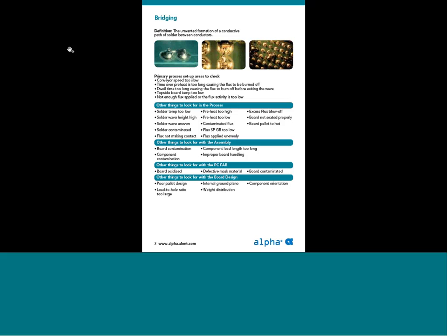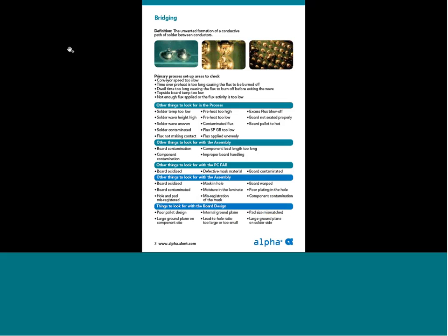Board design: internal ground plate, weight distribution, component orientation. Many times we can troubleshoot by taking a board with a known issue, rotating it 90 degrees, and running it with the exact same process, and it has no more bridging issue. So orientation is definitely important.